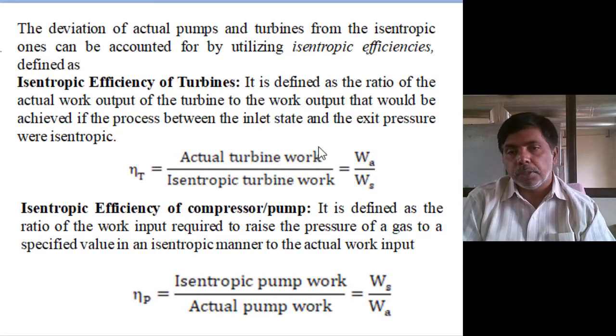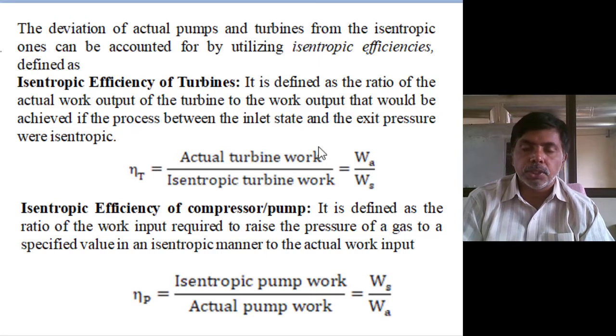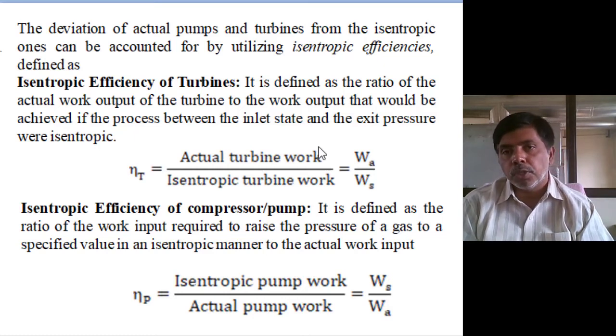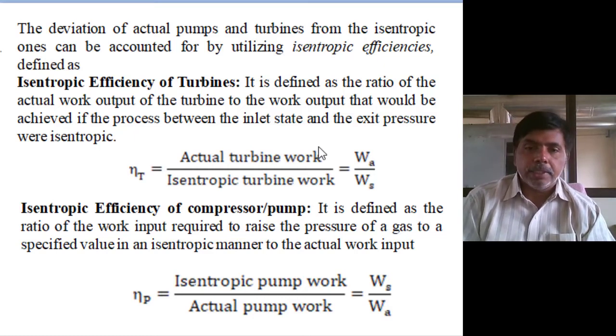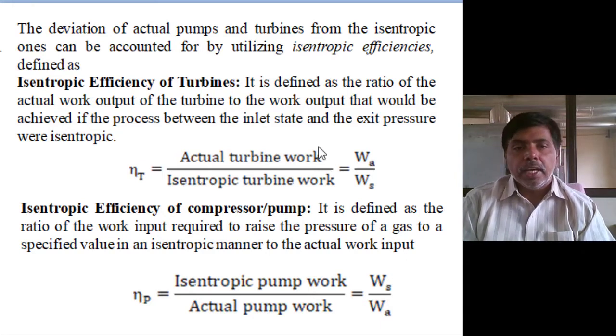Isentropic efficiency of turbine. So first, the isentropic turbine work output we calculate based on the pressure and temperature of operation. In the problem they will give the isentropic efficiency of the turbine. By using that, we calculate the actual turbine work output. Second, as I already mentioned, only high grade energy interactions we are considering for the actual, real cycle.